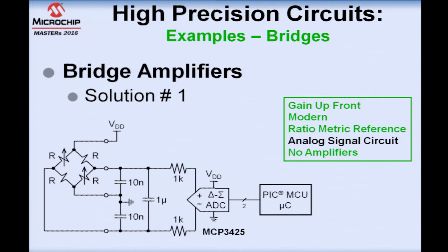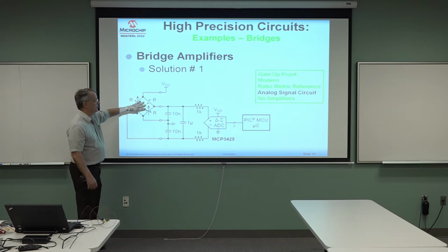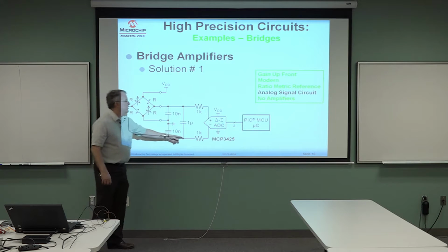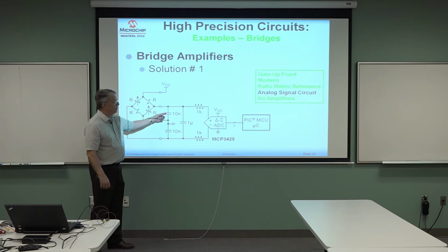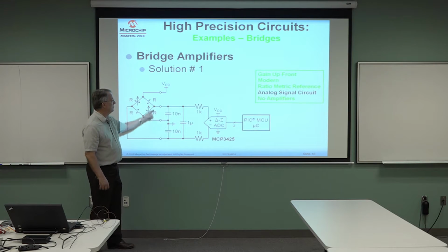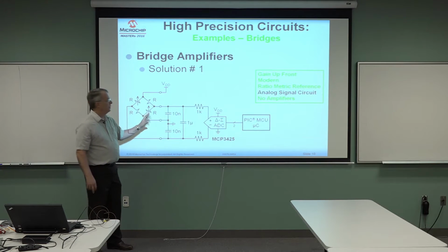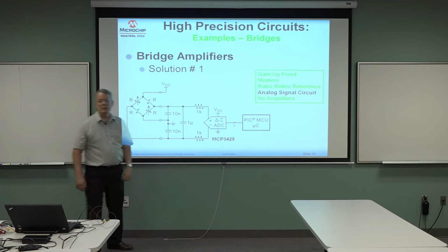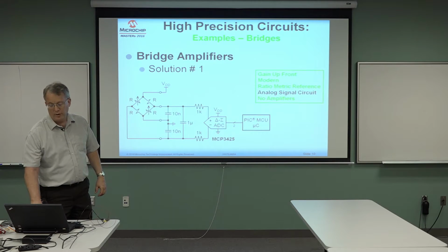The only other comment I have at this point is these capacitors filter any noise you see here. The reason for this capacitor here is to swamp any mismatch between these two capacitors. If they're not the same value, you're going to get different pulls on these two legs, and therefore you'll get a common mode to differential mode conversion, which can be a problem with very noisy environments.